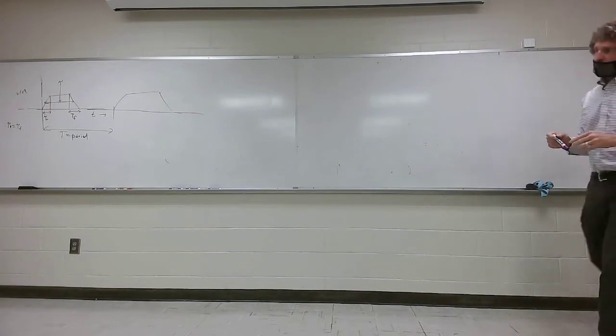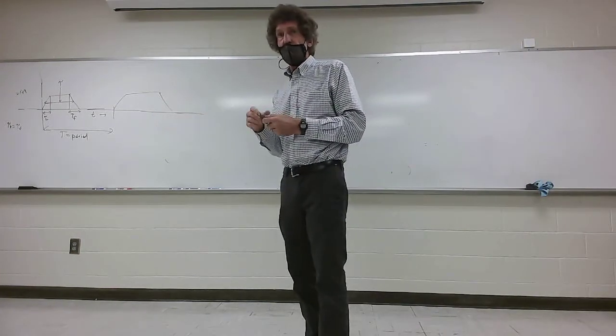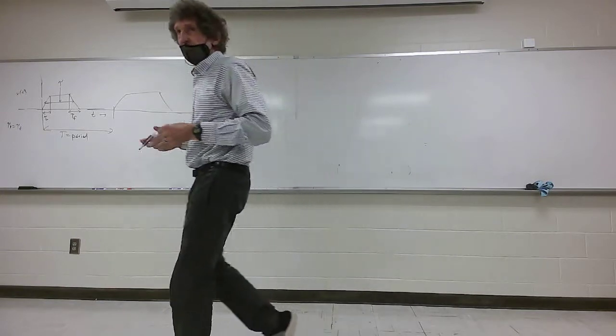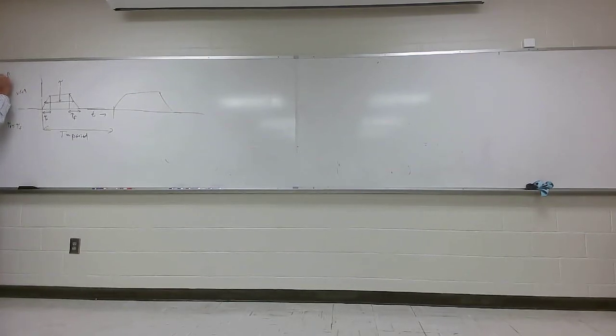Generally speaking, T is the accepted symbol in most junior level electronics courses. You all familiar with that, capital T? And in physics, I believe, they use that. So the frequency, which is called F0 because this is considered the repetitive frequency, is equal to 1 over T. So for instance, if you had a gigahertz clock, the period would be 10 to the minus 9 seconds. Now the rise time is the primary thing you worry about, and they almost always approximate it as a straight line.